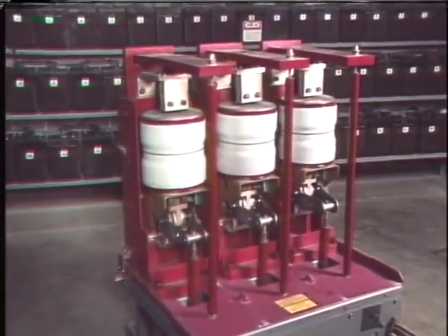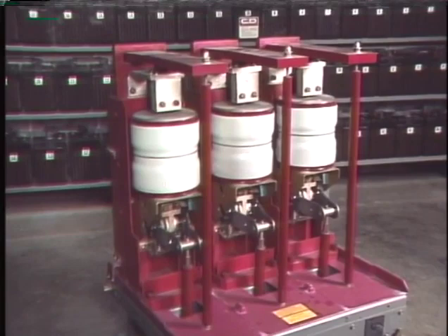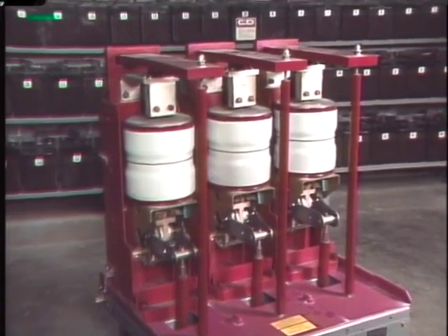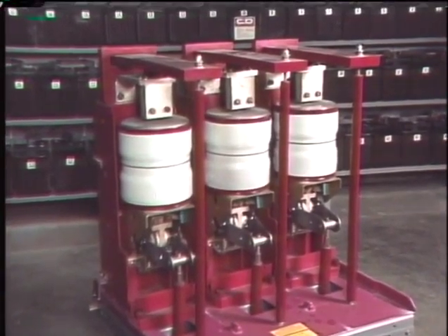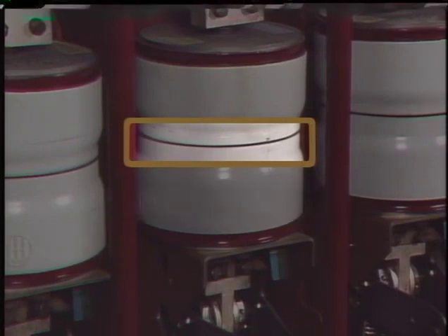The maintenance tasks for a vacuum breaker are much fewer than the tasks for an air magnetic breaker. Basically, they include cleaning the vacuum bottle and checking contact erosion. A precaution is needed here. Some vacuum bottles have a ring around the middle that may be used for testing. The ring may carry a substantial electrical charge.